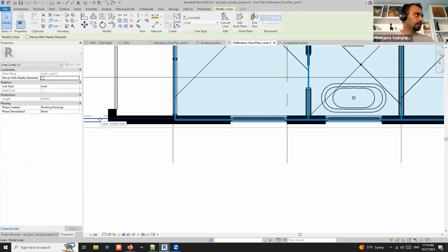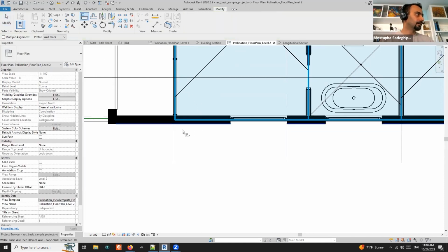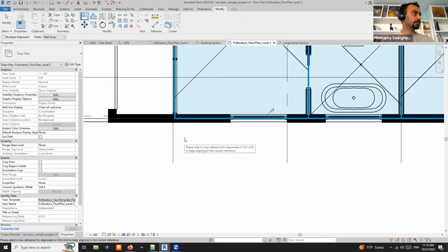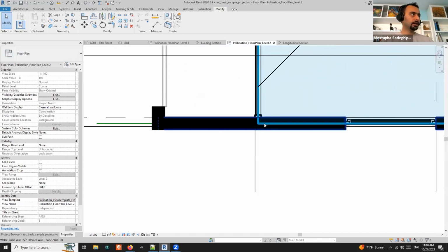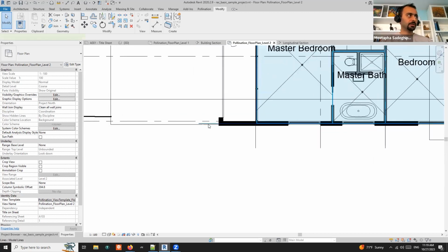And there is this command in Revit for align, AL, that does that for you. I always forget which one I should select first. Okay, I did it wrong. So you select this one and align it, and align that one to it, right? So draw the line and then make sure you align it with the middle of the wall where your rooms are. So it's here.